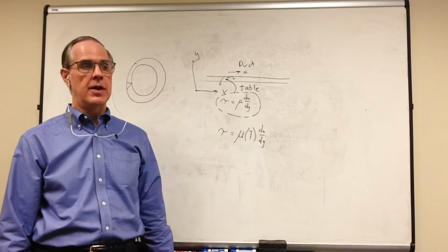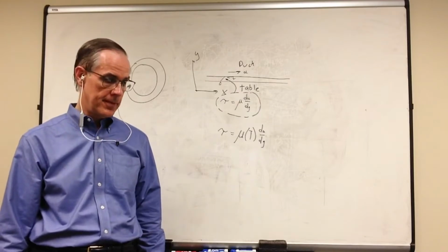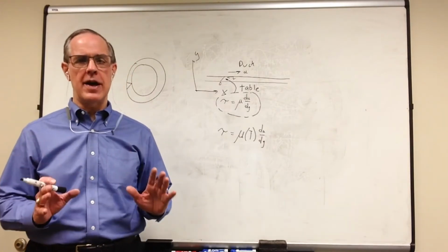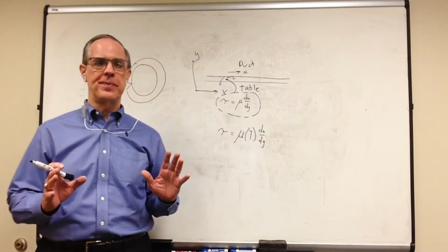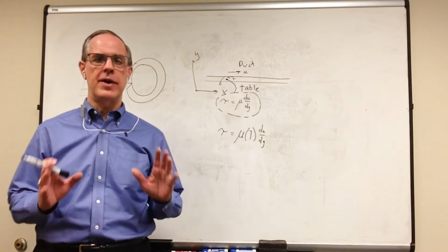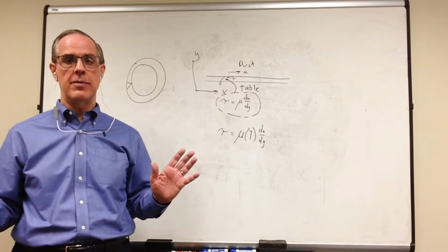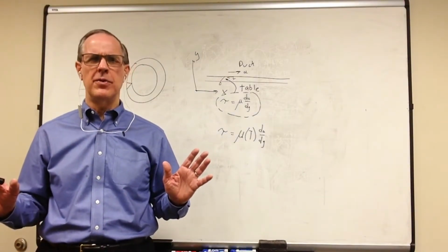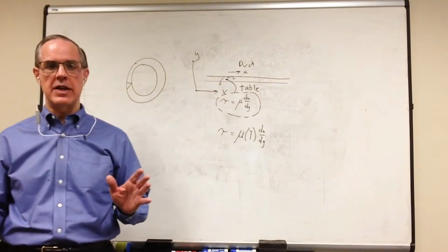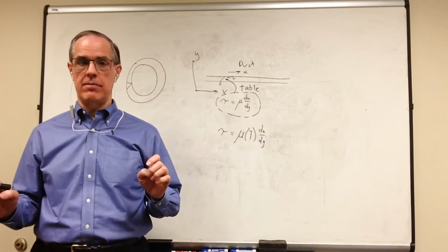And once that happens, then we have lower viscosity and lower losses, but also lower lubrication. For the purposes of this experiment, we're not going to spend a lot of time worrying about the temperature effects. That's not the primary objective. It's very possible to construct an experiment where you vary the temperature to see the different temperature effects, but that's not what we're going to do this time. We're going to focus more on the effects due to change in mu because of shear rate.